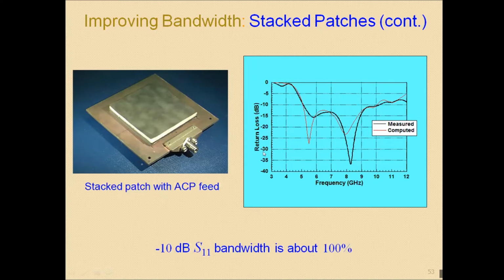That can be measured. This is the curve that we get with the help of the network analyzer, or in the simulator. If they design the antenna in software like CST or ADS, then we will get an S11 plot like this, with return loss in decibels. So the antenna result would be like this. The x-axis is the frequency and the y-axis is the return loss, that is S11 in decibels. 20 log of S11 is nothing but the return loss.